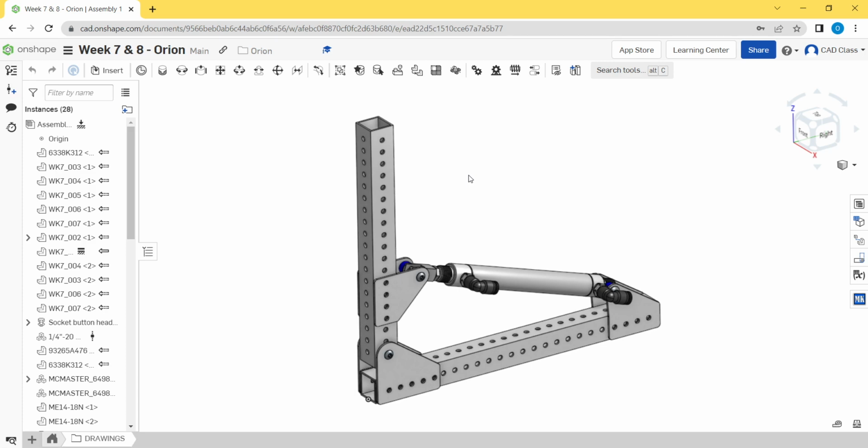Basically, many of you guys that were on the team over the past seasons will know that anytime we 3D print a part, you just pull that STL out of the CAD file and you just go and 3D print it. Anytime we cut a flat part on the router, like a bracket or something out of polycarb or aluminum, we just export a DXF and we just take it over to the router and we plug it into the CAM software and we cut the part. There's no drawing, there's no paper, there's no PDF, there's nothing like that.